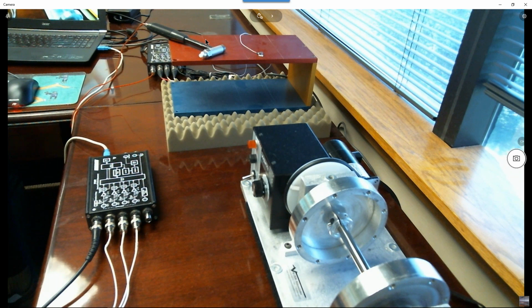Now, when you test a large structure, sometimes a hammer isn't sufficient. These impact hammers, you can buy one that is up to maybe 25 pounds, but when you're testing something as large as a bridge, you have to measure what we call a transmissibility, and it's a ratio of your roving accelerometer to a reference accelerometer.